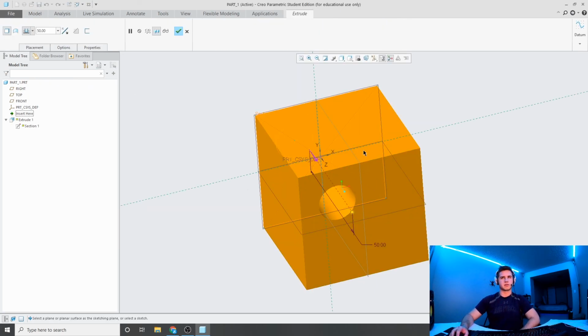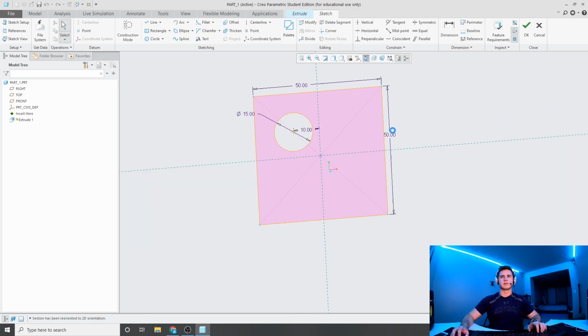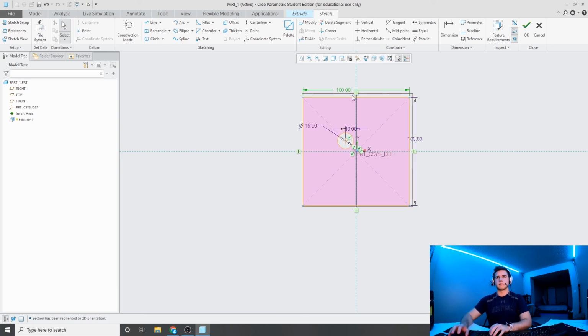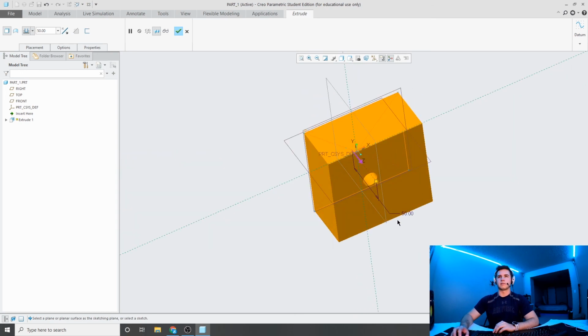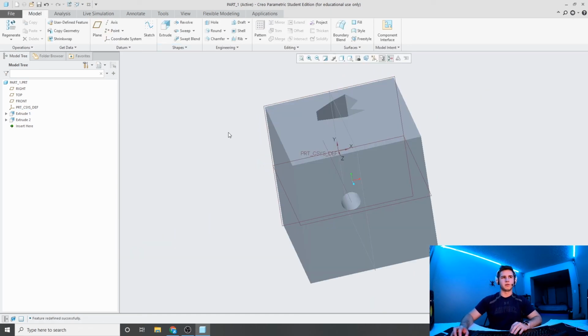See, we're back at this screen, but we can't edit the original square dimensions that we drew here. So then we'll go back into the sketch view, right click, hit edit internal sketch. Now we're back in the sketch view here. Change our dimensions to 100 by 100. Click OK. Now we've got the original square to be the dimensions that we want, but then we need to change this value to 100. And now we're there.